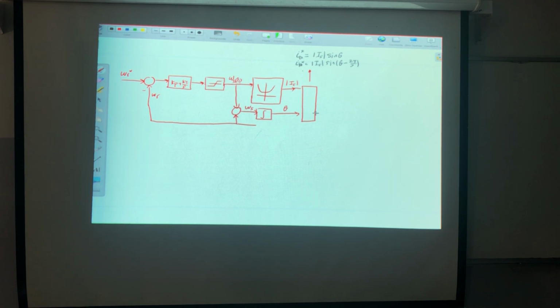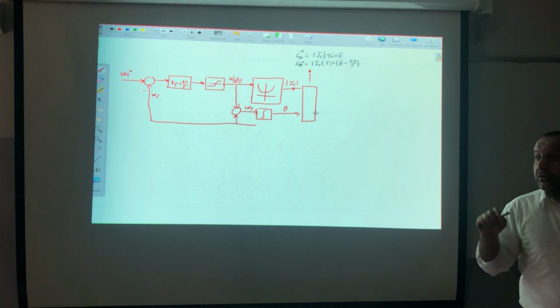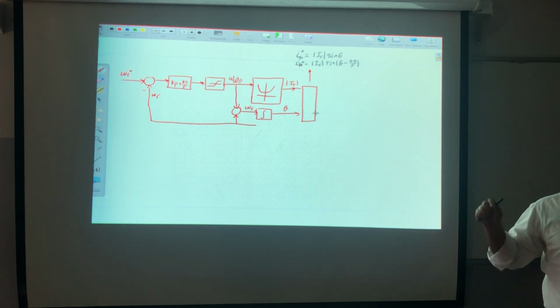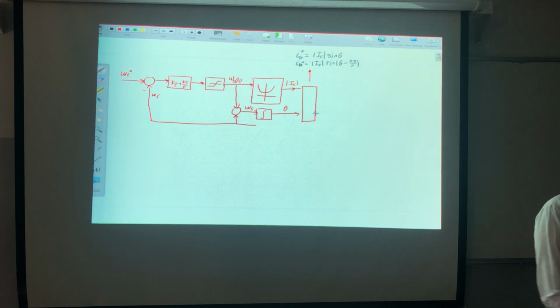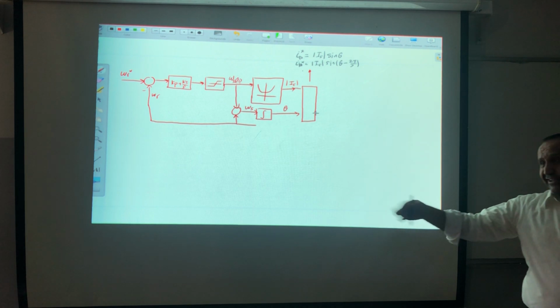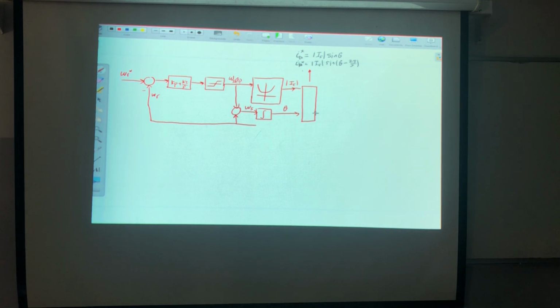But simply you know that the PI control is most powerful when the reference is constant. If the reference is alternating, it will do nothing, like SpongeBob. So simply this will shrink the options to the hysteresis current control. So I need to do current control, which will be hysteresis current control.